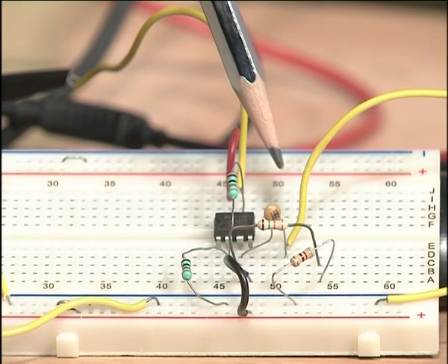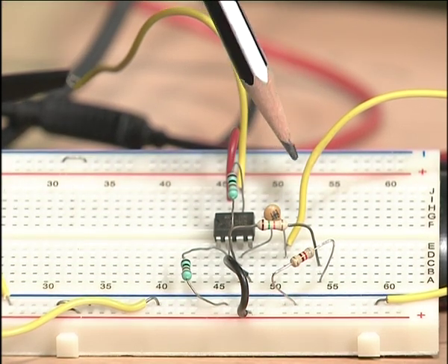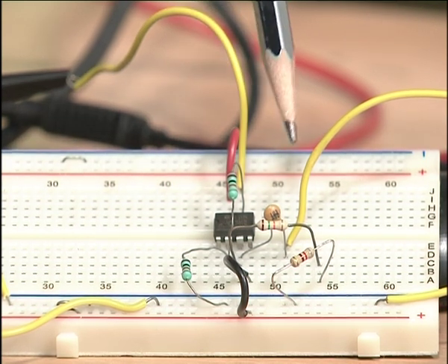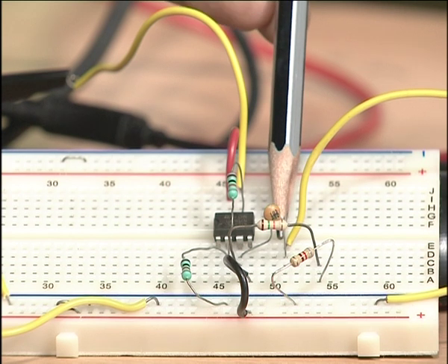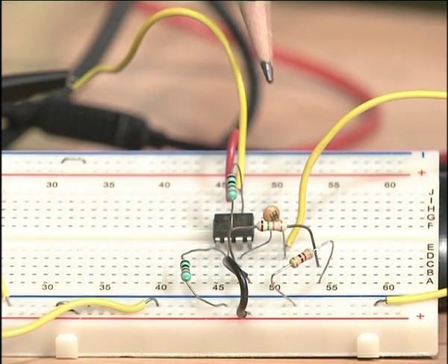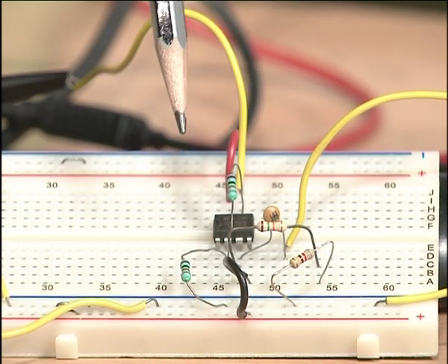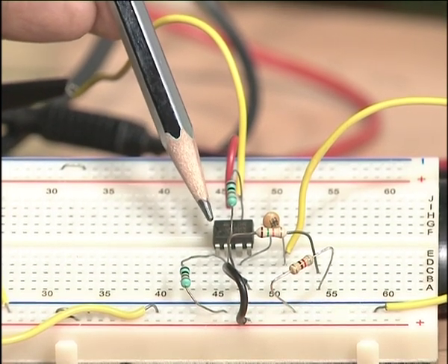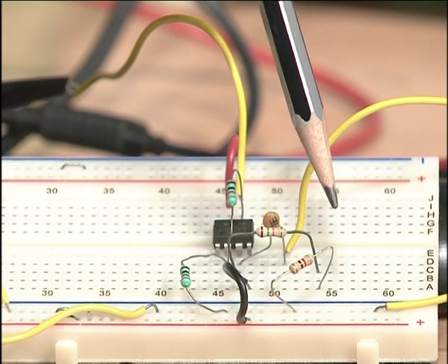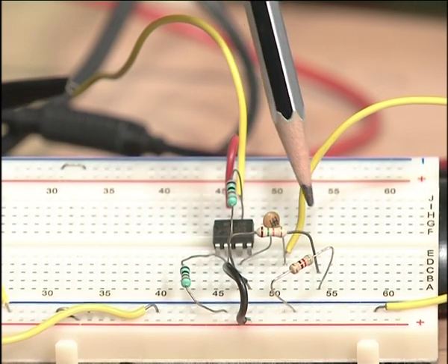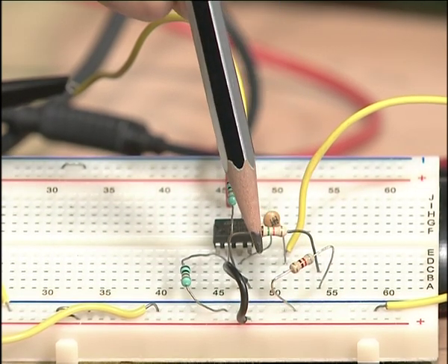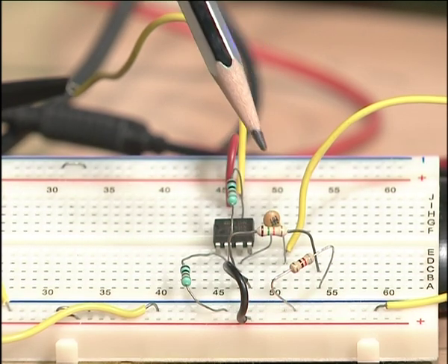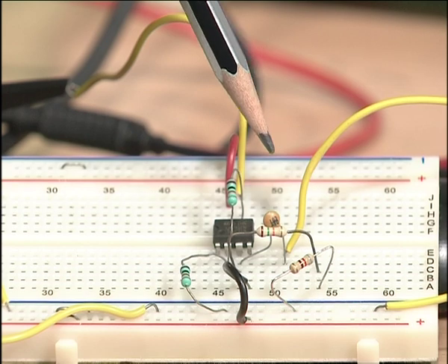So, the passive RCs which constitute the low pass filter: the input signal here is now connected to the capacitance, one terminal. The other terminal here is connected to the third pin, which is a positive pin. Now, from the positive pin what we have is the resistance here. So, there are two resistances in series that is connected to ground here. The filter is now configured for 1 kilohertz cutoff frequency.